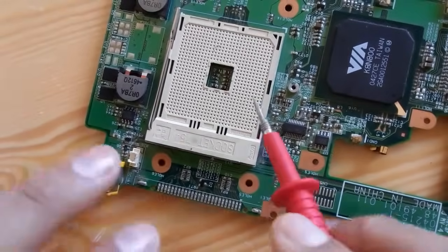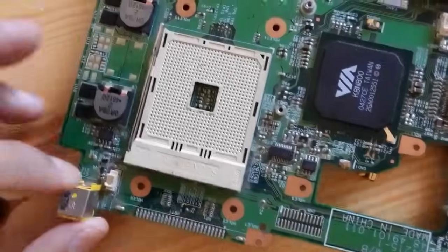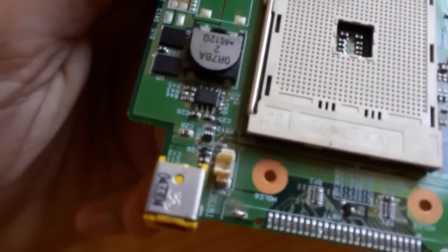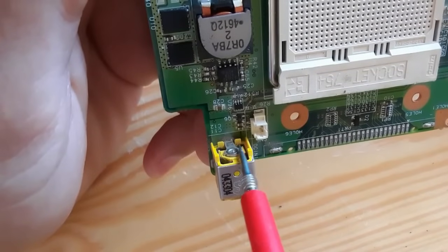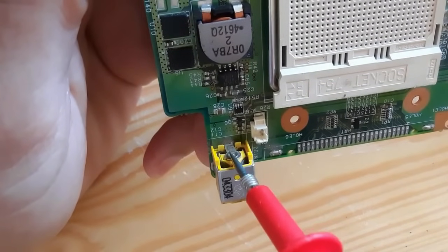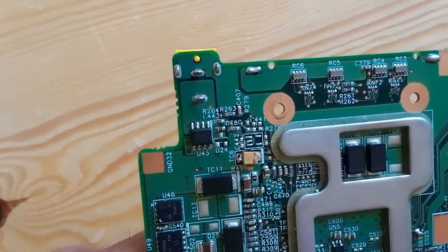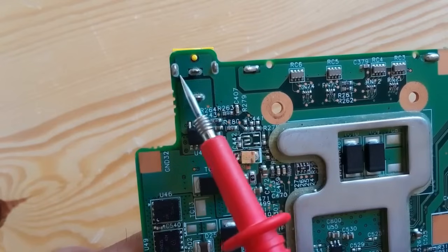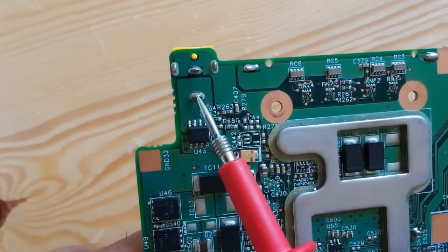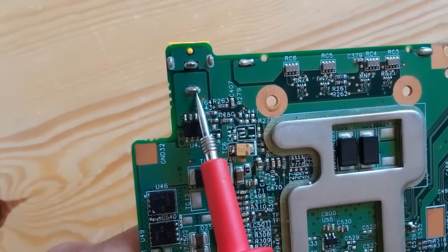Okay, so here we have another motherboard. Of course, I will show you many motherboards in order to go deeper into understanding the motherboards. Here we have a power jack for this motherboard. As you can see, we have the positive terminal connected to the motherboard. On the other side, as you can see, we have the terminals. You should always check the soldering or the solder state. If you find a dry joint in any terminal, you should apply new solder, of course using the soldering iron.